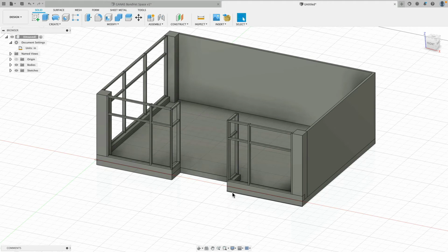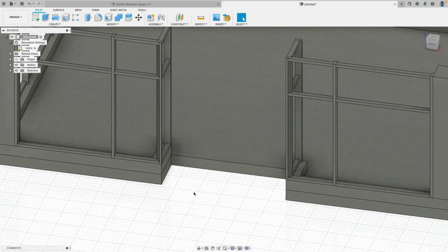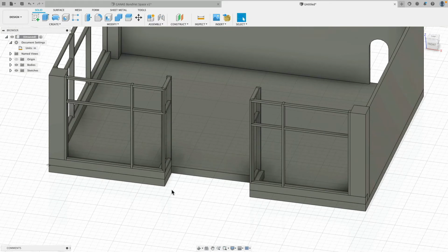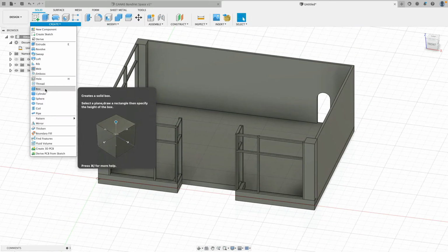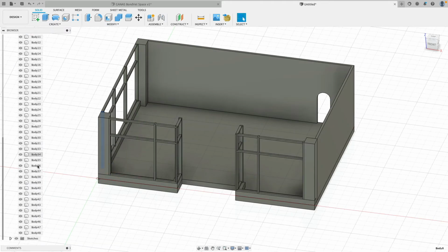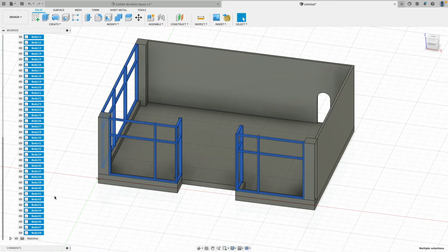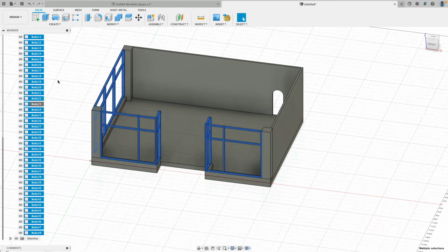And then it's time now to do the same also for the door. So to do the door, the easiest way would be to build actually from the center to the outside. So this is an edge, and the edge somewhere has a midpoint. Okay. I will actually, hold on, escape. First, what we will do is we will select all these and we want them to be inside a new group. If we right click here, it says move to group.